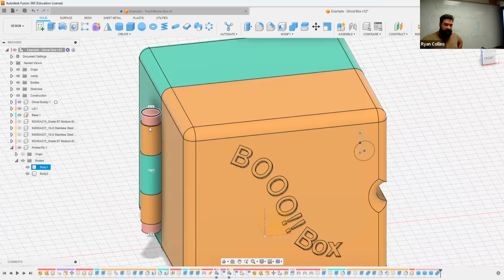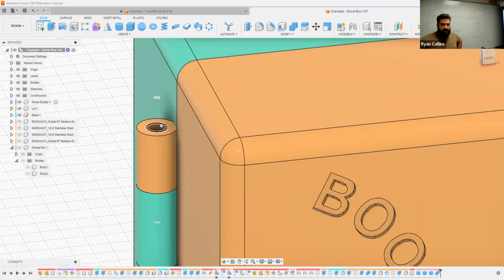You might not even need to make this whole thing with a flange and such. You could just probably drop in a pin and glue it in place on either side. Speaking of, the other thing you could do would require more work. You could go back in and shrink this aperture for your original model. Filament is 1.75 millimeters that we're printing with. There is a different size, but 1.75. You make your aperture more like 1.8, so you give yourself a little bit of clearance, print it, slide a bit of filament through, and use a soldering iron or something, and just burn the two ends together. Now you've got a pin locked in place.